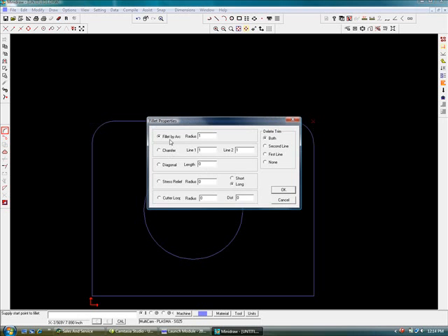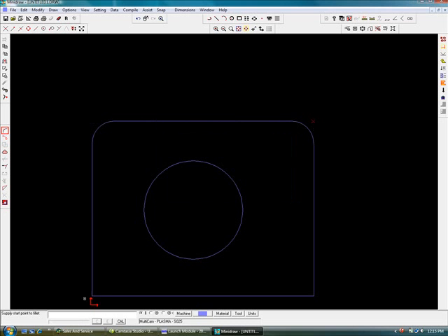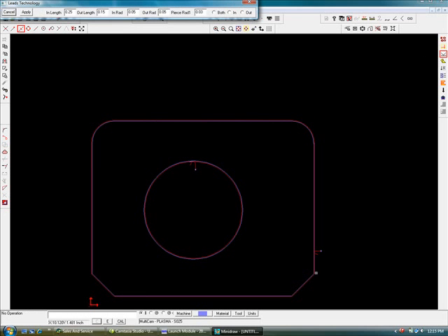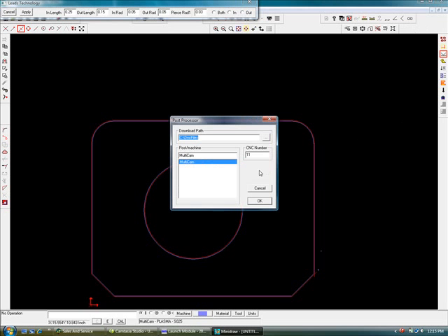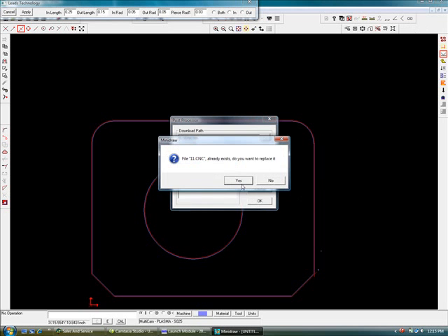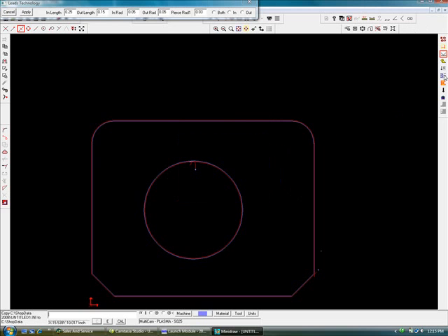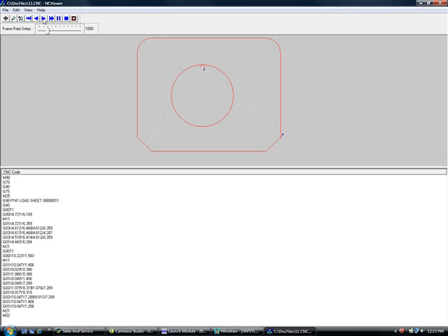And then I'm going to change that now from fillet to chamfer, 1 inch by 1 inch. Click OK. There again, click on the corner. Click on the corner. Apply a toolpath, put the lead in, lead out anywhere we want to put it, and there we go. Now if you'd like to post-process and do one part at a time, you can just simply post-process from this part right here. And here is your code to run the machine and your NC viewer.